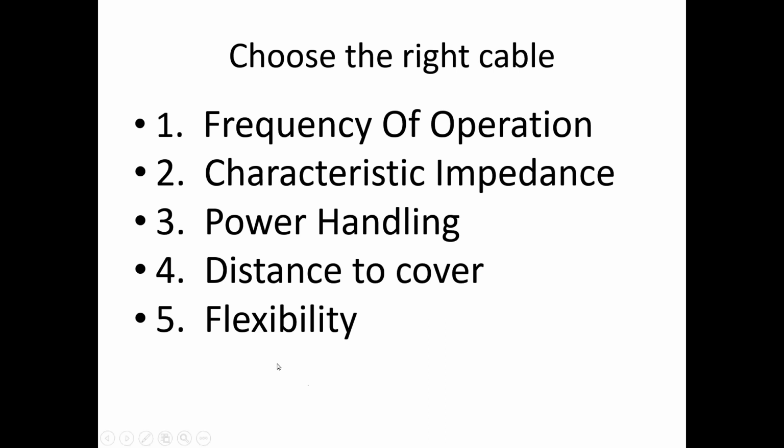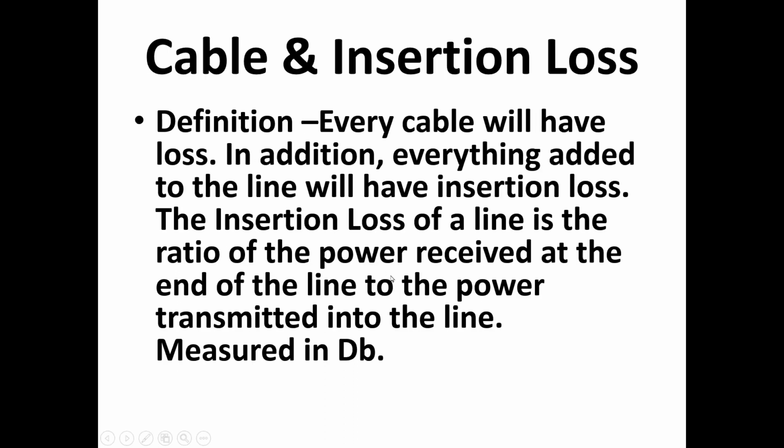So as scientists and engineers put all of these things together, they have to remember where it's going to be, what the cable is doing, and basically what they have to do to make it work. All right. When you have a cable, everything that you put into that cable will cause insertion loss. You put a connector in there, you put a meter in there, no matter what you put in there, it's going to cause additional cable loss to whatever the cable itself had. And again, this loss is measured in decibels.